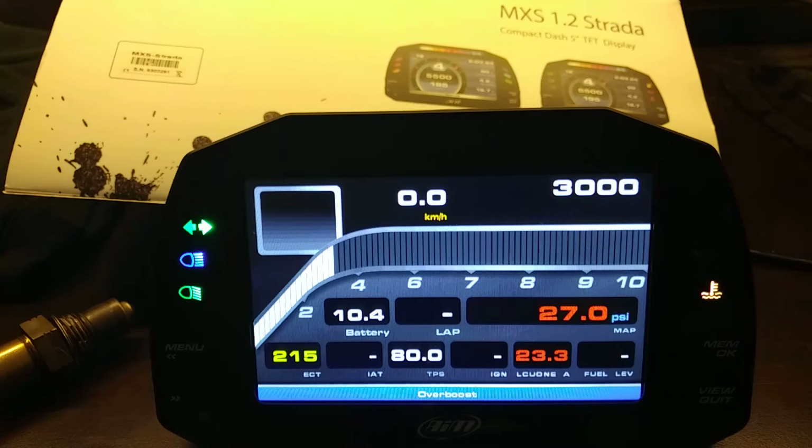However, if we have an oil pressure of 20 psi, it will show a low oil pressure warning indicated by this red flashing icon here. Because the RPM is above a certain amount, it needs a certain amount of oil pressure that the user can configure. Obviously, this will prevent some false alarms from occurring before the motor is started at 0 RPM when there is no meaningful oil pressure.